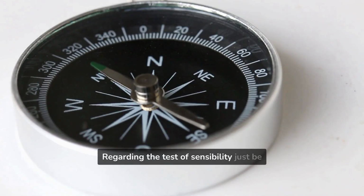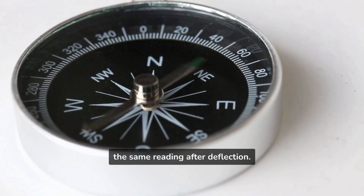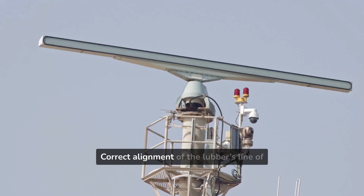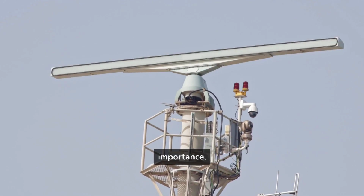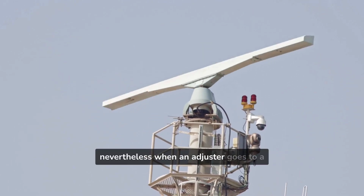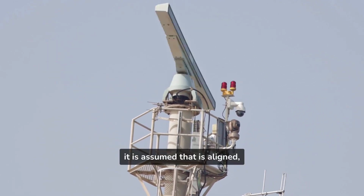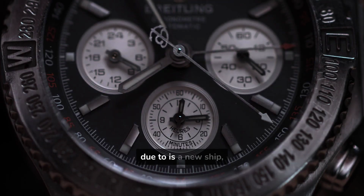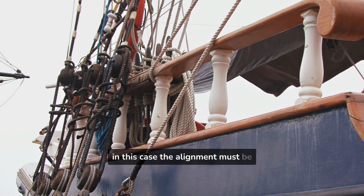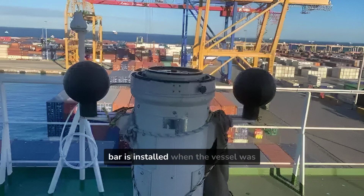Regarding the test of sensibility, just be sure that the compass card returns to the same reading after deflection. Correct alignment of the lubber's line of the compass with the fore and aft of the ship is of paramount importance. Nevertheless, when an adjuster goes to a vessel which has the compass already adjusted, it is assumed that it is aligned. Only if the binnacle must be installed, as on a new ship, must the alignment be done properly. The Flinders bar is installed when the vessel is built and the adjuster has nothing to do